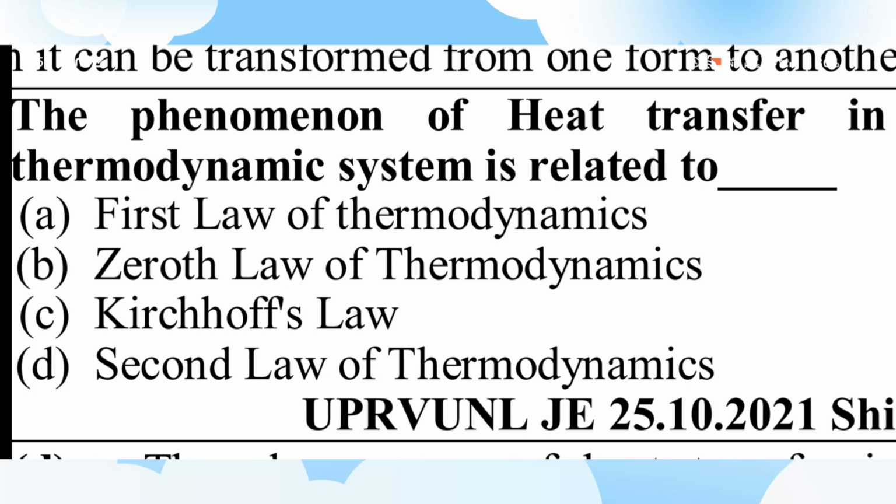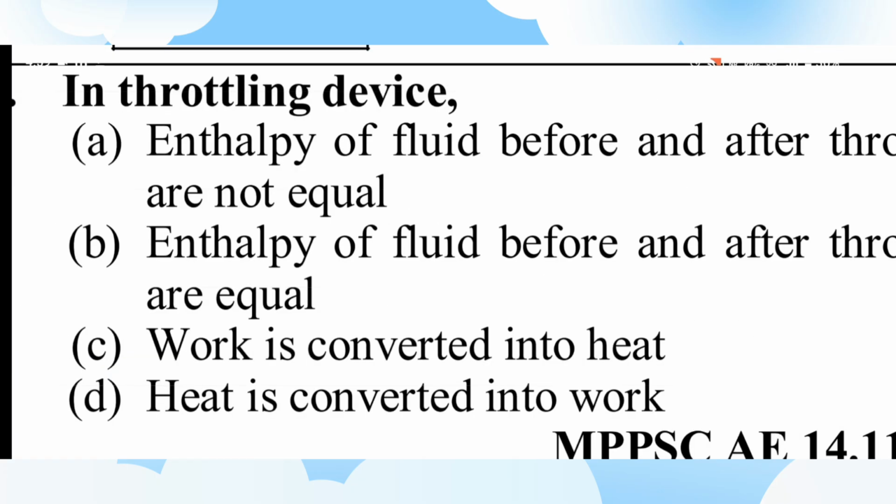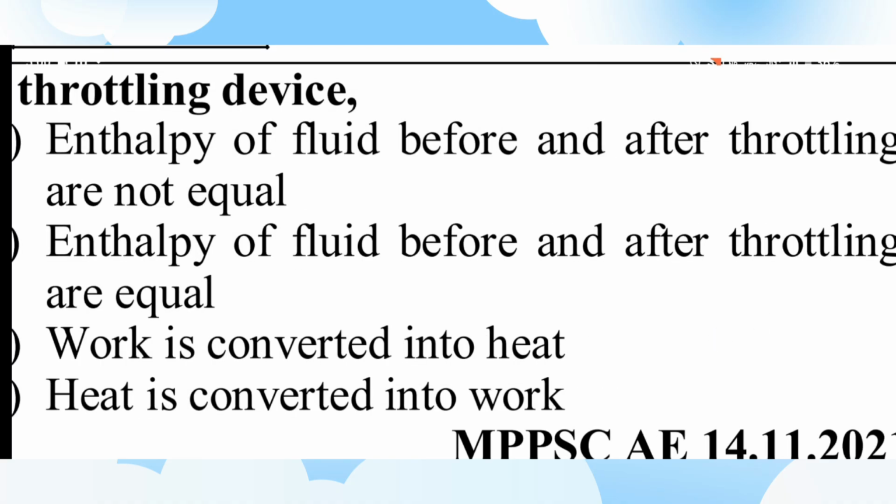Friends, next question: the phenomenon of heat transfer in a thermodynamic system is related to A first law of thermodynamics, B zeroth law of thermodynamics, C Kirchhoff's law, D second law of thermodynamics. D, second law of thermodynamics. Next question: in a throttling device, A enthalpy of the fluid before and after throttling are not equal, B enthalpy of the fluid before and after throttling are equal, C work is converted into heat, D heat is converted into work. B is the answer: enthalpy of the fluid before and after throttling are equal.